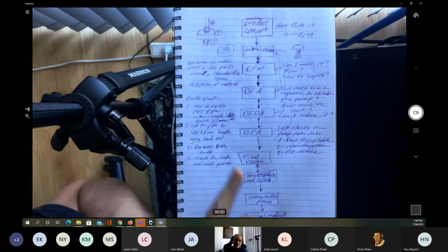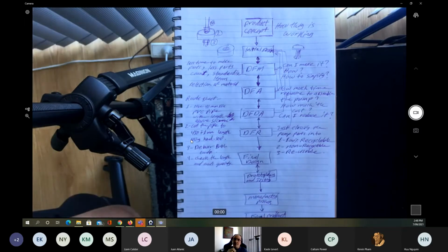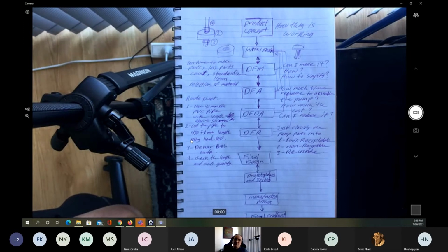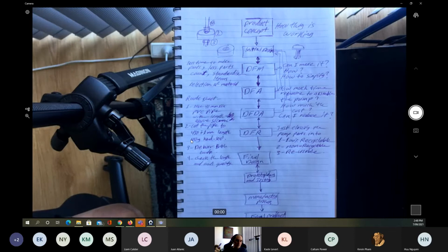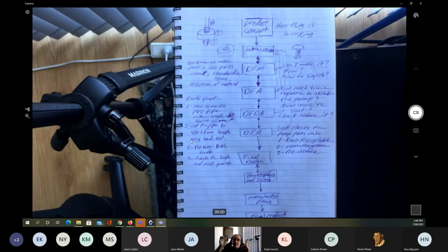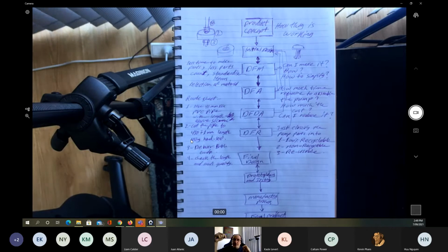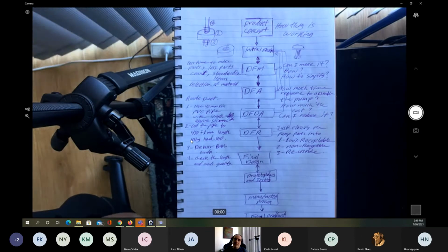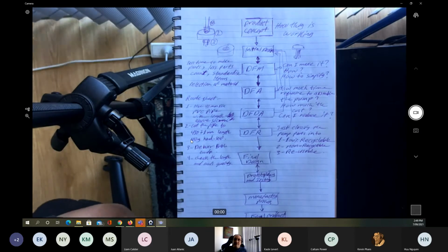Just a reminder, for every route sheet, we usually put in a hand sketch, because we send that to someone who's going to make it. We need to write down the hand sketch about the original pipe. That's what I would like to have: 450 millimeter plus minus 1 millimeter, and put an arrow on the end to show that this end needs to be delivered.